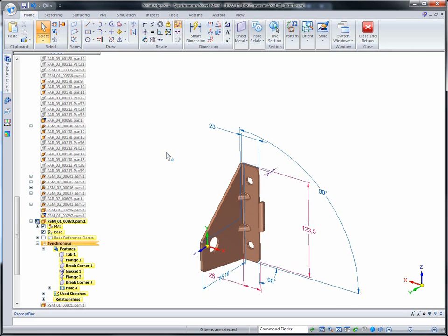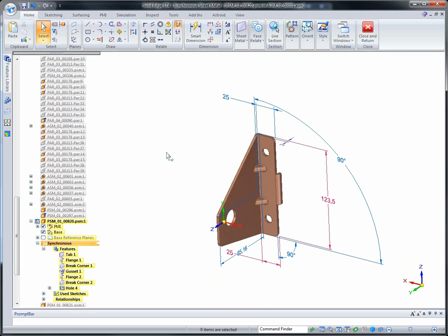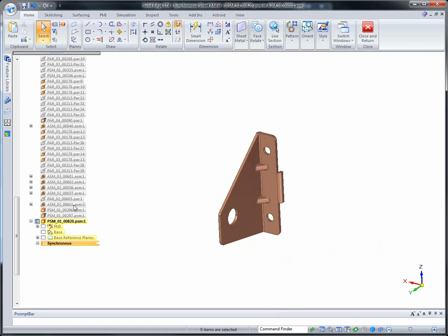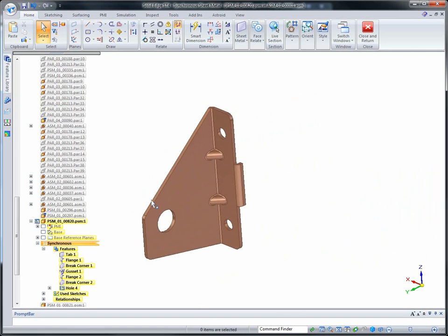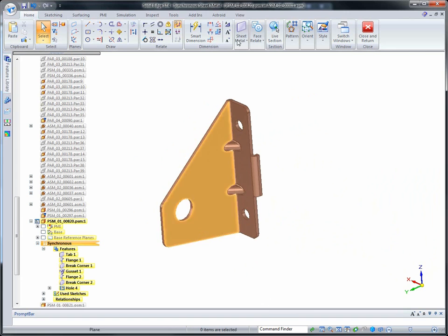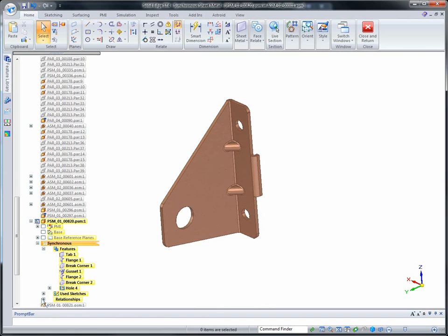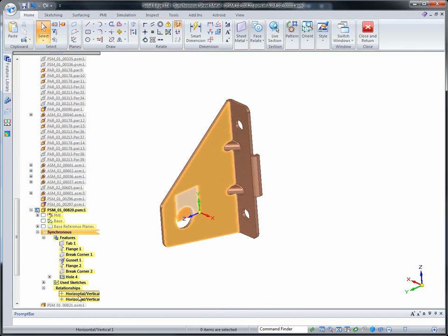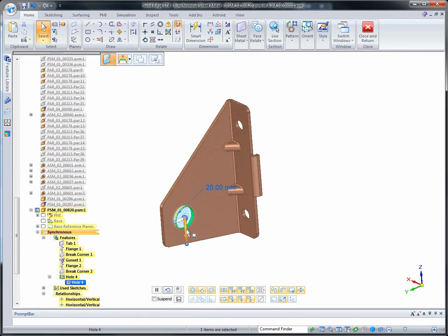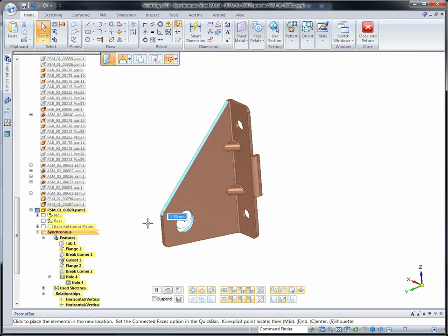Another thing that we may wish to do is align the center line of the center point of the mounting hole for the roller to the midpoint of the bracket. Again, the new relationship that we have in Solid Edge ST4 allows us to do that very quickly and easily. This becomes a persisted relationship such that if we move the hole in the bracket, it's going to change the midpoint as well. So using the steering wheel, we'll just begin to drag that and you'll see this change.